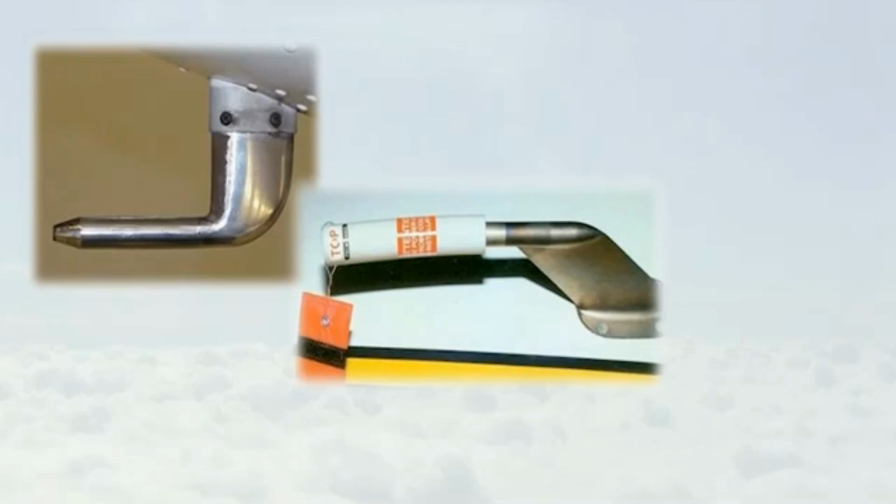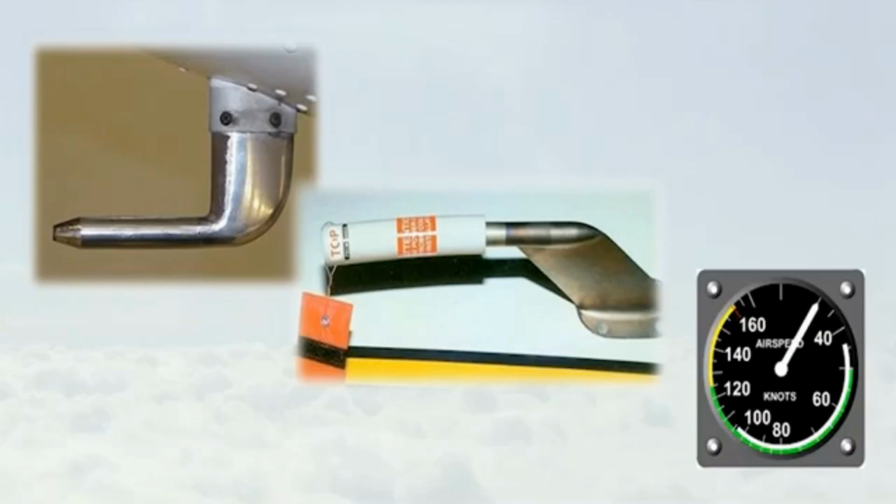Next, if one is fitted, the pitot head heater must be checked to see that it is operative. The instrument dial glass must be clean and undamaged. Finally, the instrument should indicate airspeed in the correct sense shortly after starting the takeoff run.